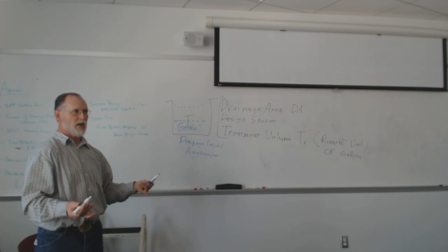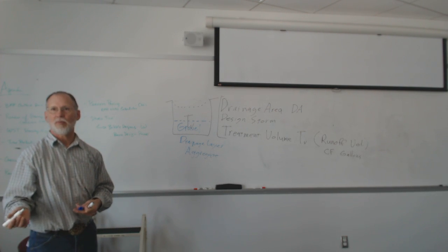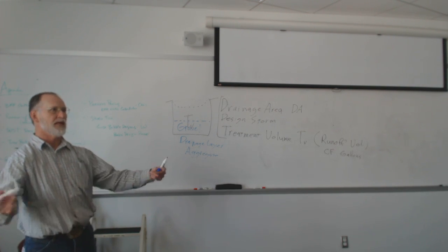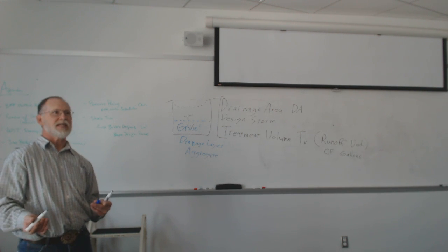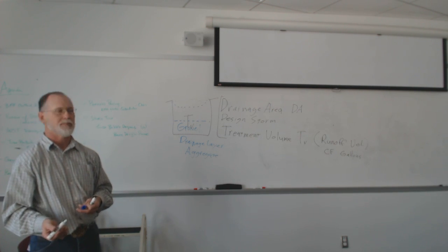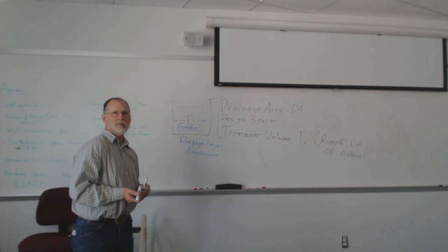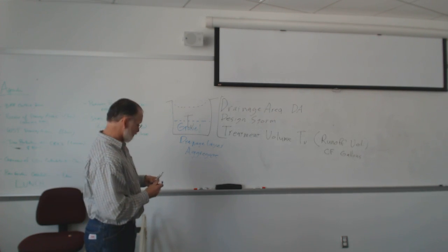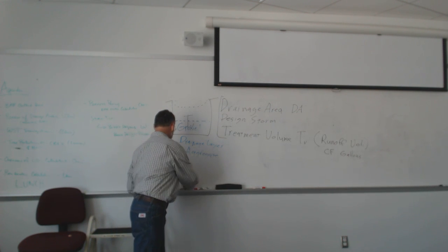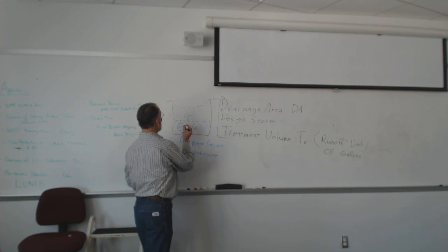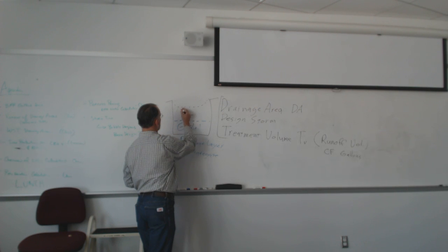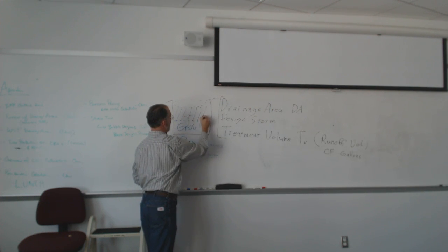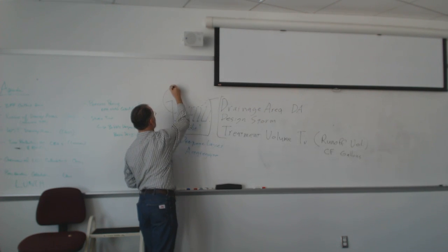So number 57 is a Department of Transportation standard that we pretty conveniently use. We'll use different grades from different times, but in general, we want a stone that's open graded. Water will flow through it easily. Then above that, if it's bioretention, we're going to have this stuff.